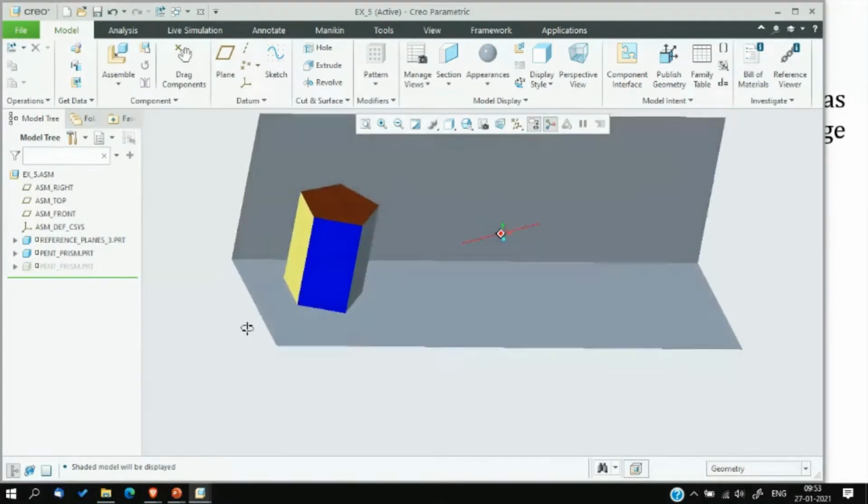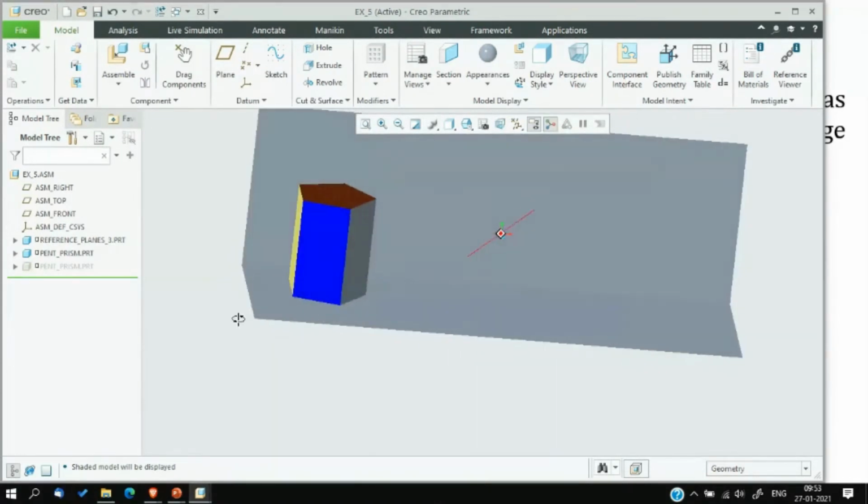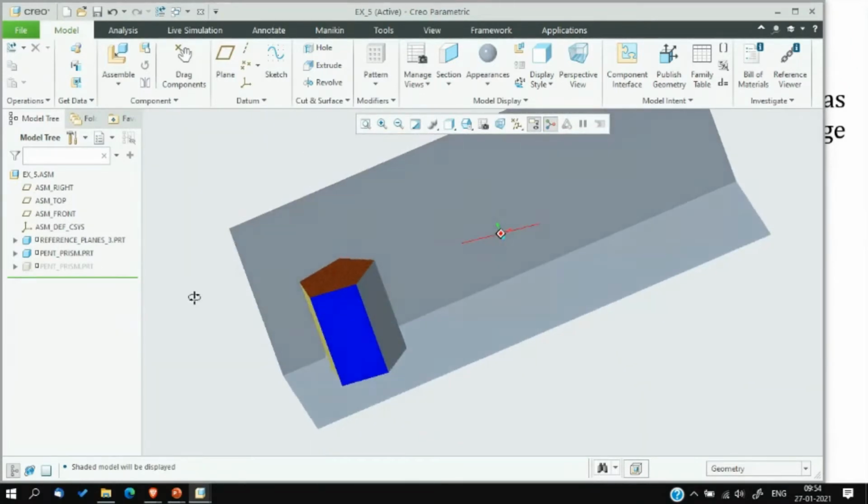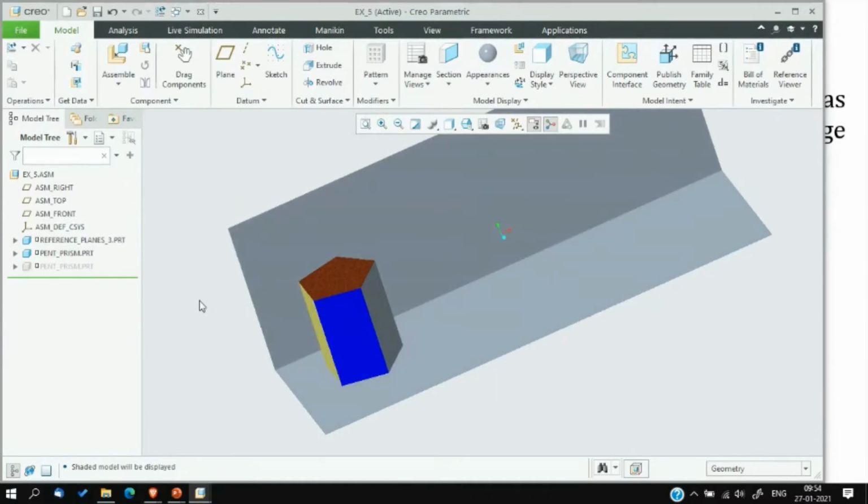In the simple position, which we call when the axis is perpendicular to one of the planes, it is resting on HP with its base on HP. Why is its base on HP? Because it has to rest on one of its corners.